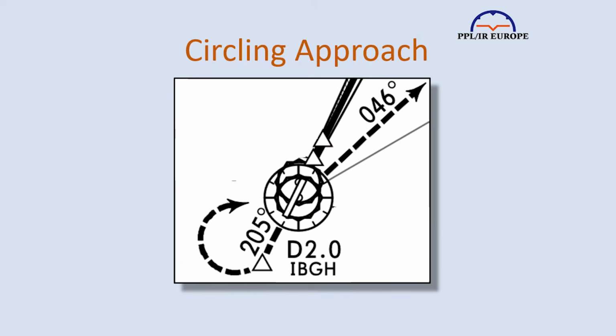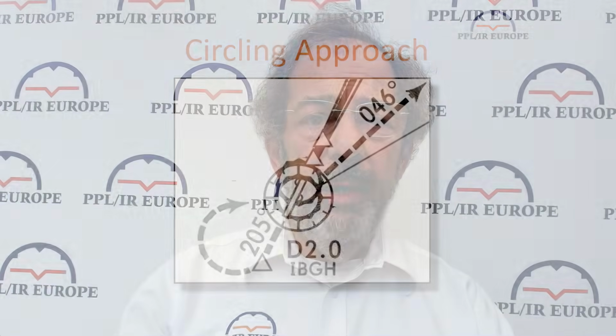This is a classic example where aviate, navigate, communicate is vital. Once you're pointing the right way, you can execute the missed approach. Obviously, if the missed approach entails a turn back, it makes sense simply to continue into that, once above MDA and still within the manoeuvring area. You should always have thoroughly briefed the missed approach, of course, but never more so than before a circling approach.